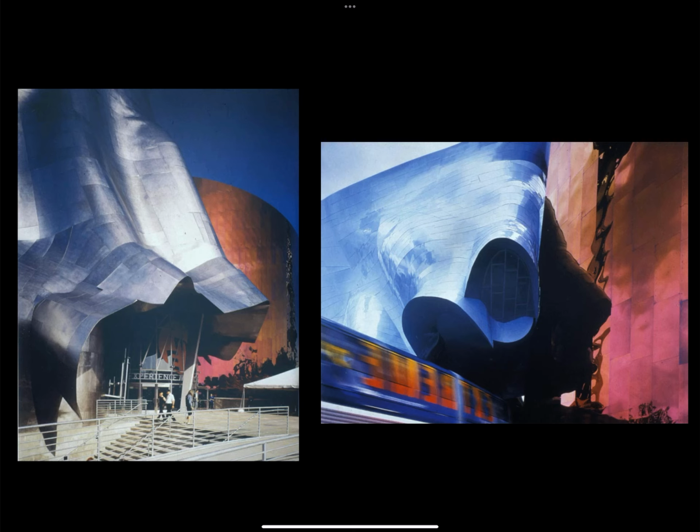So if we choose dark colored metals, or we make metals dark coated through the coatings that we apply, those will absorb the heat and light of the sun and increase the running costs of the building. If we choose light and reflective colors, these will reduce the amount of heat absorbed by the metal cladding and will reduce the heating and cooling costs of the building.